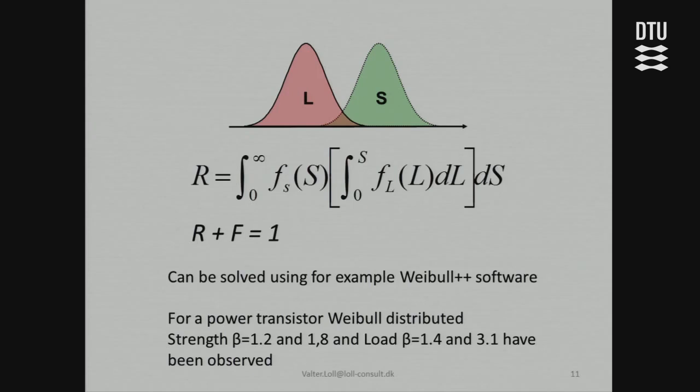We had another problem at Bang & Olufsen with the flexible snap block, which should keep the printed wiring board into place. They broke because they have to keep it into place, but they also have to take the load when the customer was pushing the buttons. And we could show by simulation and calculation that we could not, with the tolerance of the PC board, be within the fatigue limits of the plastic parts. So what we did was we divided the function between a part which would just keep the PC board in place and a fixed stop which would take up the load, a very rigid stop.